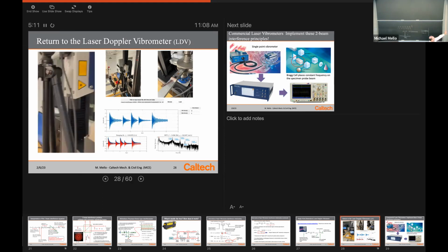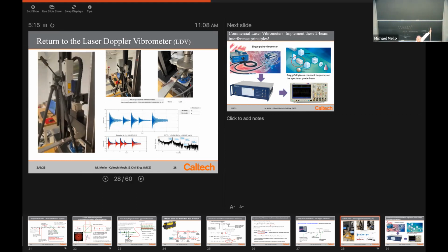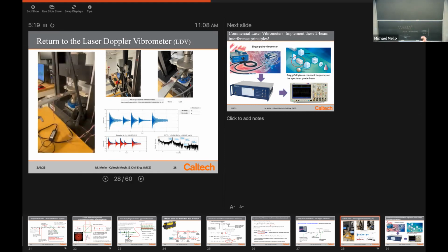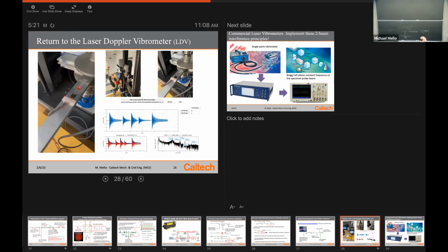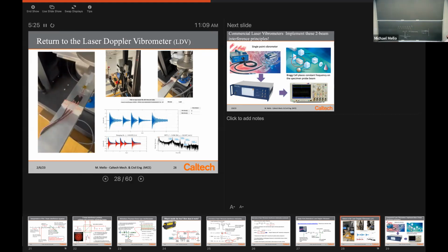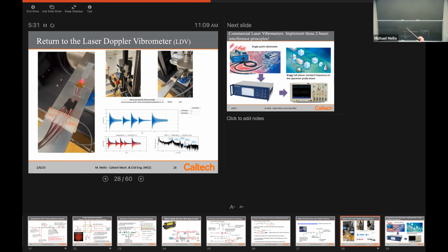And then up, I'm trying to just sort of show you where the vibrometer is sitting, looking straight down on the beam. And then I'm just going to pan around the room and maybe show some other aspects. This is a nice close-up view again. By the way, this is the retroreflective tape. Really helpful to put that tape on there whenever you can. It really aids in the amount of light that comes back to the device.